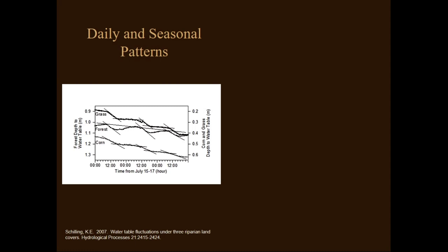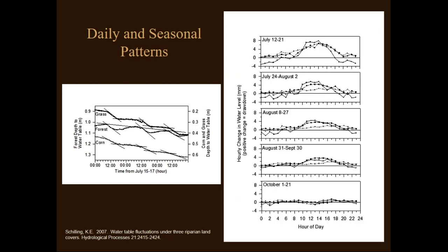You got these diurnal patterns under the forest, and what I was observing was more of a step pattern in the grass and the corn. And what was more unique about it was just doing this ET analysis on an hourly basis. You can see when the plants start transpiring, we get a big change in water table level during the day, it closes up at night, and you can see how the seasonal response diminishes. So that's this idea about maybe using water table monitoring to estimate some things about ET.